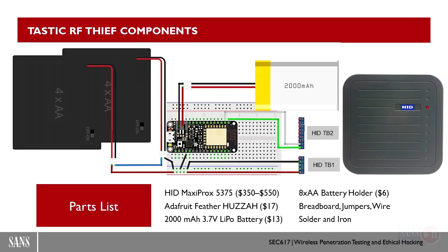It was a super simple circuit to build with 3 components. And then if we want to use different batteries or a different device that requires different voltage, you pull that circuit, you put a new one in. So if you want to do 5 or 3.3 volts, we have the components slottable within the device, taped down so we can swap those as needed. Super simple. Okay. Some other things, maybe even some improvements. But we are now able to capture Wiegand data from real reads of cards, and then we can potentially, at distance, take that data and use our Proxmark to update those as well.